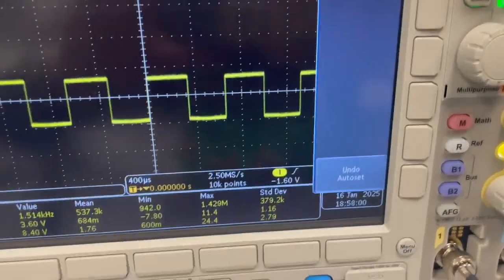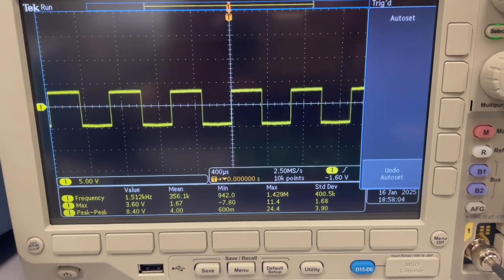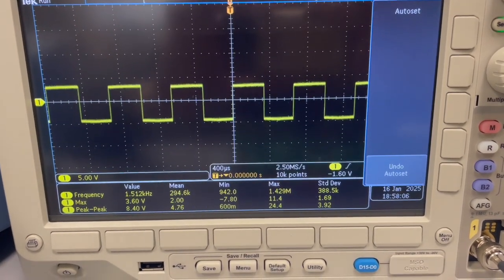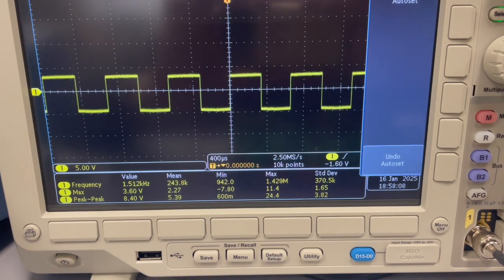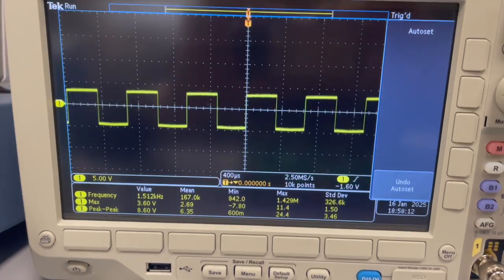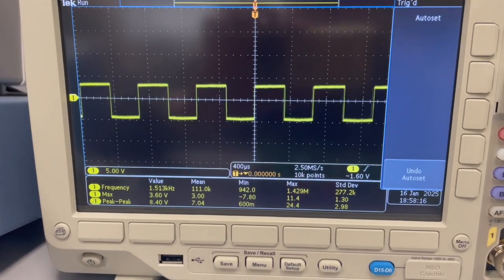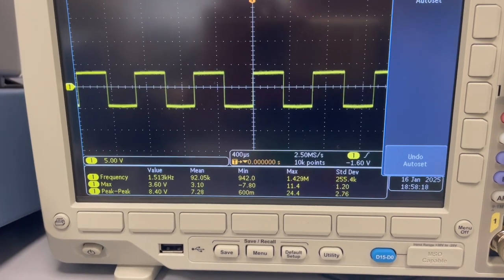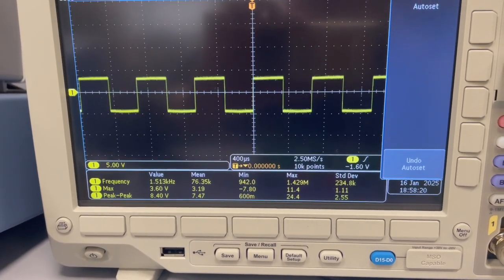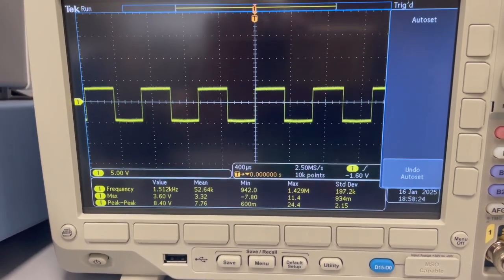And as we can see here, this Astable Multivibrator can produce the perfect square wave signal. So the power supply is 10 volts, and at the output we're having the 8.4 volt peak-to-peak square wave. Remember, we should have some room for the signal, so we don't get 10 volts, we're going to get less because of biasing. So there is some room of 1.6 volts actually.